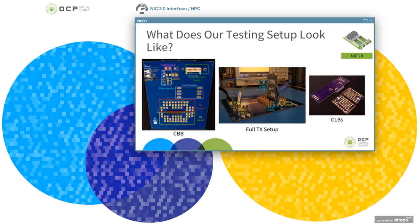In the middle is a picture of our full transmitter testing setup, which is very similar to a normal PCIe transmitter testing setup. The NIC is first powered on and begins transmitting at Gen 1 speed. It's then cycled through all waveform presets for each active lane and all supported speeds, being tested for each to ensure it meets the PCIe standard.